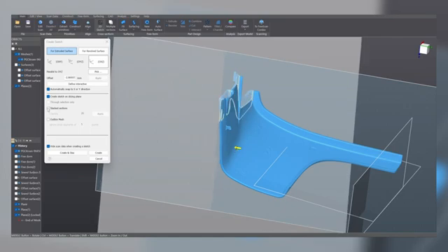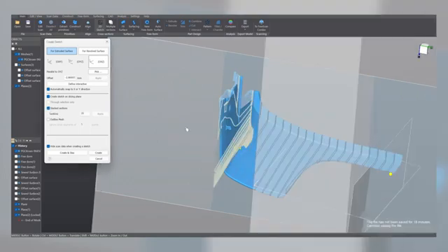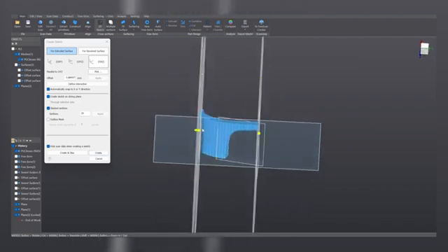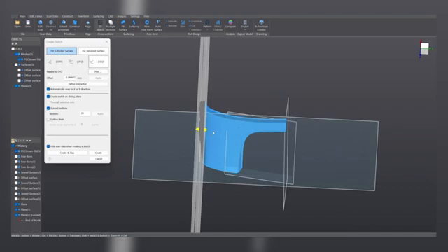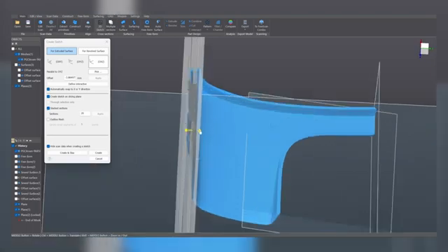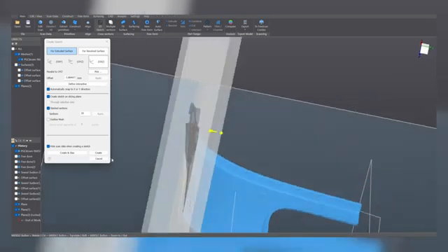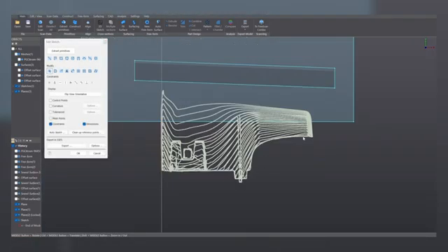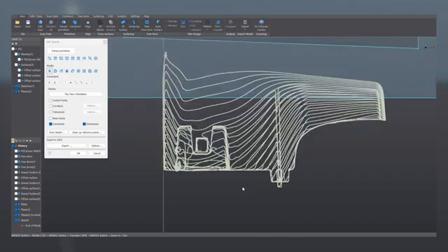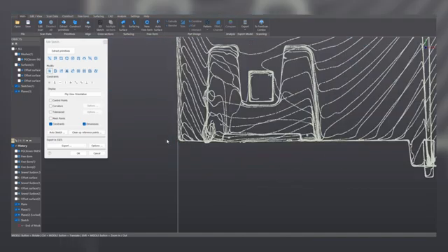So I'm going to show you a trick. Simply go to Stack Sections and move this volume until you compress all these 20 sections on the region of interest. So you have all the information here with a lot of density, and therefore you can clearly see the result that you were looking for.